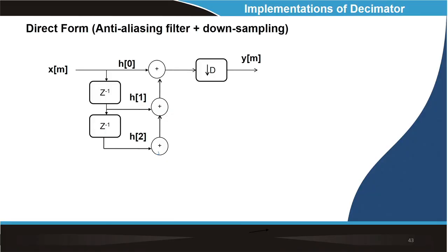Okay. In this class I will talk about how to implement this multi-rate conversion system, whether it is downsampling or upsampling. So now we talk about how to implement it. Whether it is downsampling or upsampling, this side is nothing but a filter, and this filter is nothing but an FIR filter. If I say FIR filter, it can be implemented this way, with delays.